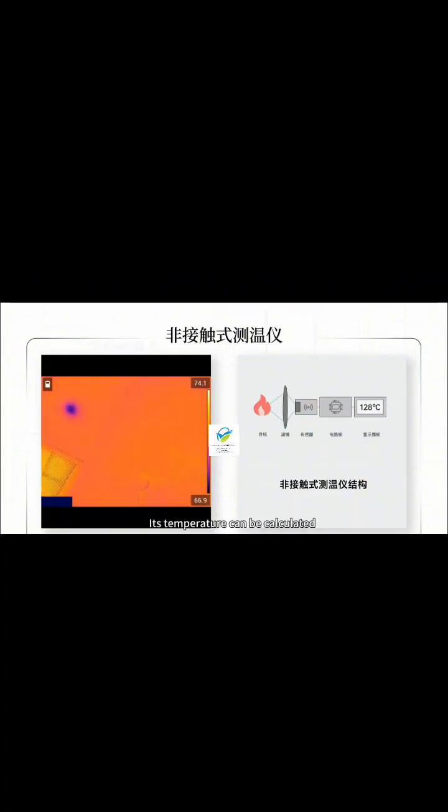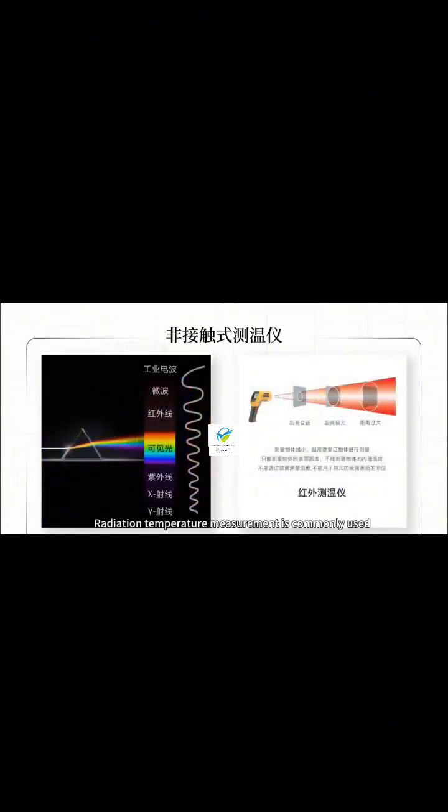Its working principle is based on the thermoelectric effect, and the main components are two metal wires of different materials, which are welded together at the temperature measurement end and the hot end. When the temperature changes, an electromotive force will be generated between two metal wires of different materials in the circuit at the ambient end and the cold end, so that a certain amount of current will be generated in the whole circuit. This electromotive force is proportional to the temperature difference, which calculates the temperature at the measuring end.